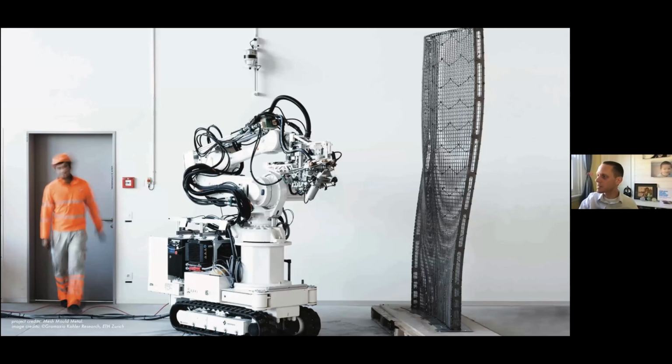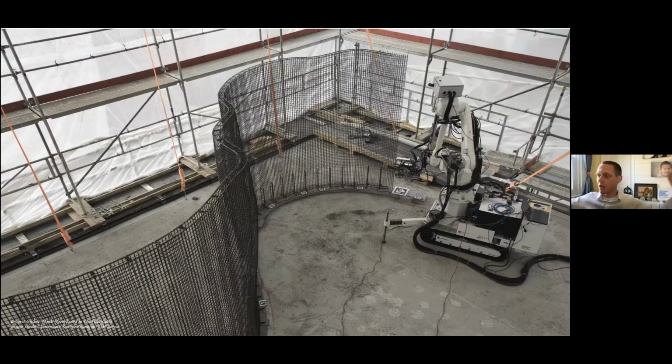And here you can see this is another project that Gramazio and Kohler's research worked on, where the robot bends the concrete rebar, and then the concrete is placed directly in the rebar. So you need zero formwork. This is a zero formwork concrete structure, which can allow them to create really flowing structures that have almost no waste in the production process. They pump the concrete into this, and they formulated the concrete so it doesn't slump out the bottom.